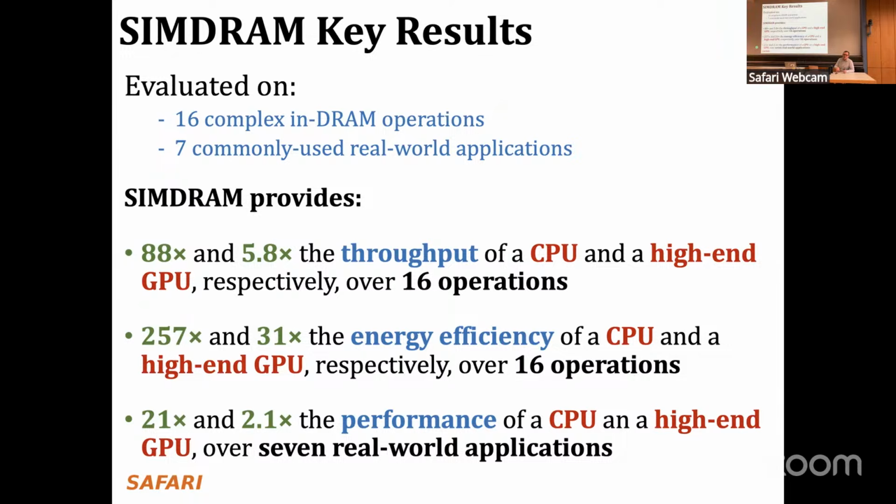The latency of the multiplication is quadratic with the bit width of the multiplication. So if you're doing 1-bit multiplication, it's not that bad. But if you're doing 64-bit multiplication, it's pretty bad because you have quadratic latency. And the paper has energy and latency of those operations. So this sort of substrate is much better fit for low bit width operations, where you're doing, let's say, 2-bit multiplication, 4-bit multiplication. Even 8 bits is a bit too much, maybe, sometimes, right?